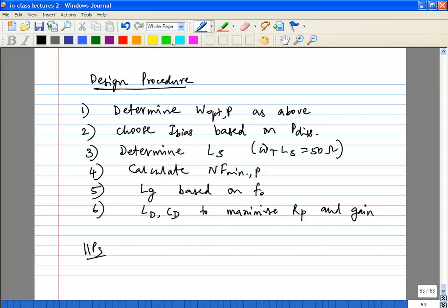Yes, so that is common mode noise. So far, we have not talked about common mode noise, supply noise, or ground noise. So far, we have talked about intrinsic sources of noise. You are right, if you have a case where your substrate is very noisy, your supply is very noisy, in cases like that, you might want to choose differential topologies if it is absolutely necessary.